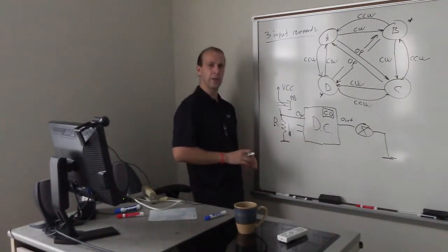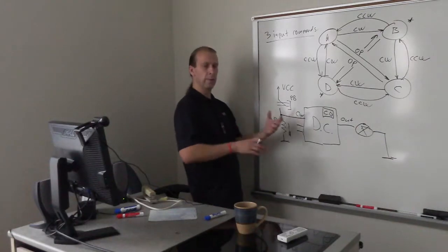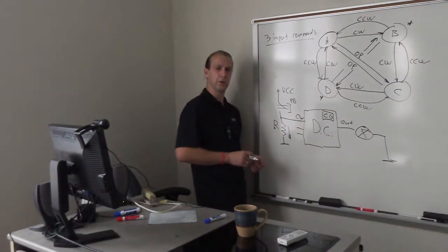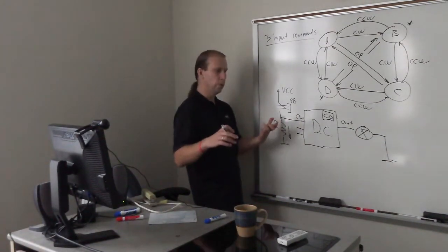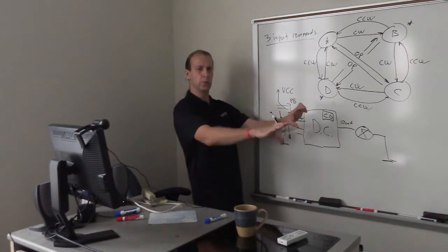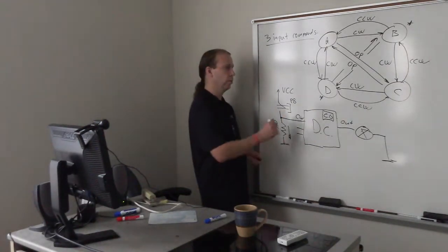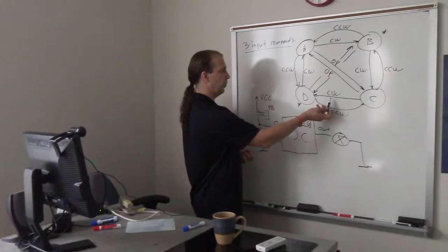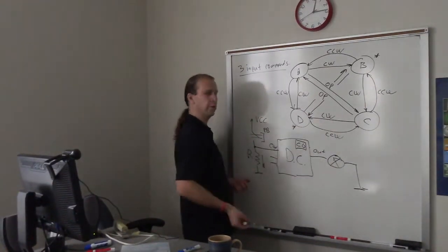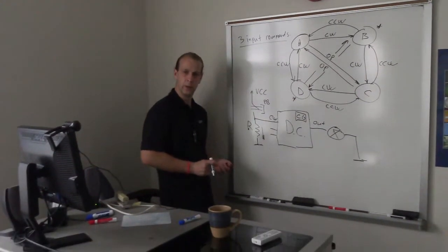This is more logical behavior rather than to come up with some strange logic. Because what will be the command if we press 2 push buttons at the same time? In other words, what should we do if we give clockwise and counterclockwise commands at the same time?